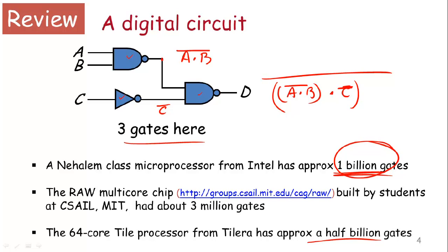And the reason all of these gates can function correctly is because of the key noise immunity property that, as I connect a bunch of these gates together, each gate is cleaning up the input. Okay, if I get VIH here and say a VOL level value from some other sender somewhere else, then it is incumbent upon me that if I produce a 1, I have to produce a VOH, and if I produce a 0, I have to produce a VOL.